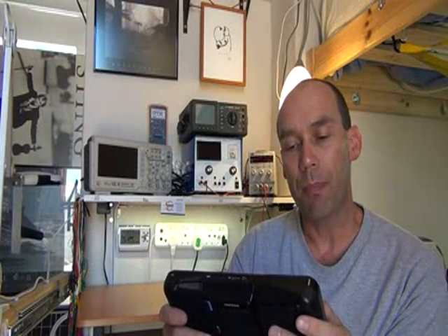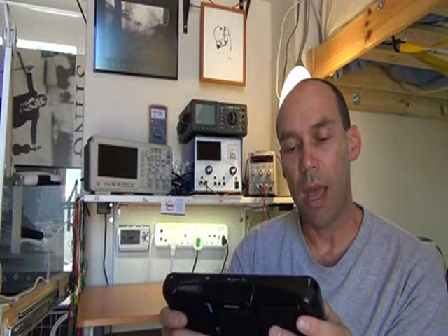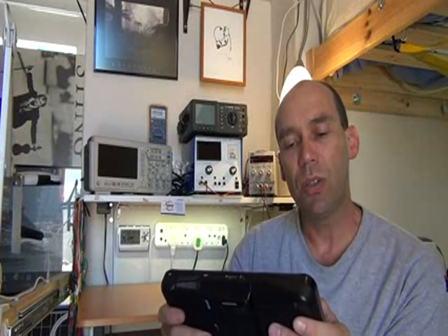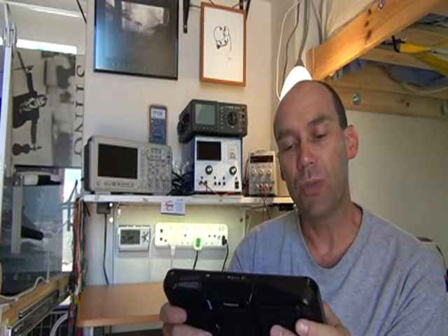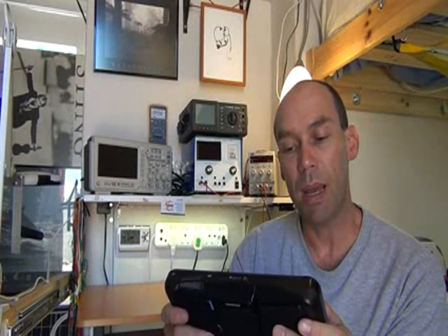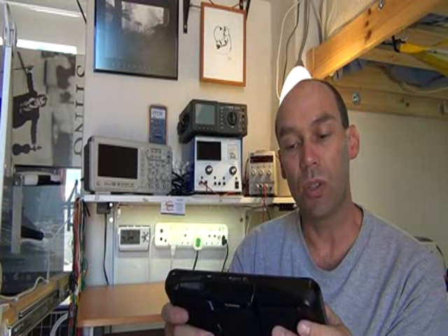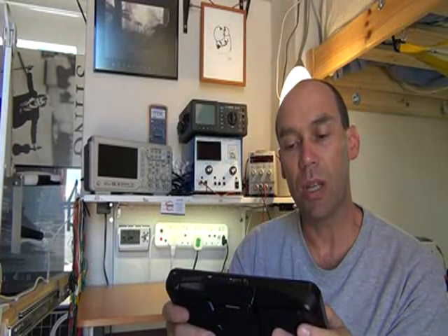And then probably the most correct answer was Kibby 15, and he said it's easier to adjust the voltage of AC using transformers. You want high voltage for long distance transmissions to minimize power loss in the lines. However, you don't want those high voltages delivered to consumers. It's a lot more difficult and expensive even these days to adjust voltage levels of DC. And that is probably the most correct answer, because in effect that is your problem.